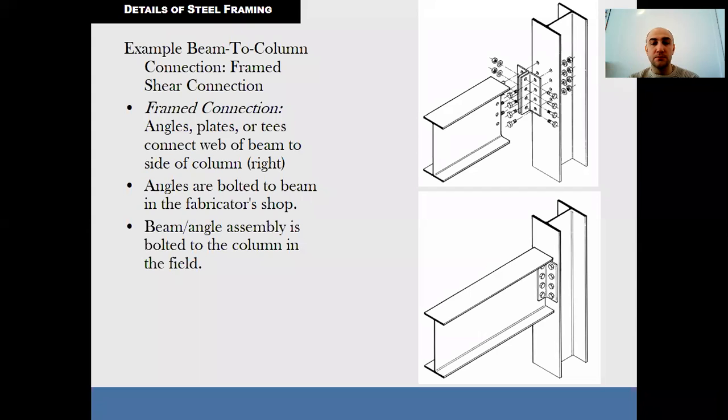For normal design, there are many procedure checks for all parts of beam-to-beam and beam-to-column joint connections, using special pieces for connection: angles, plates, special bolted or welded angle plates.